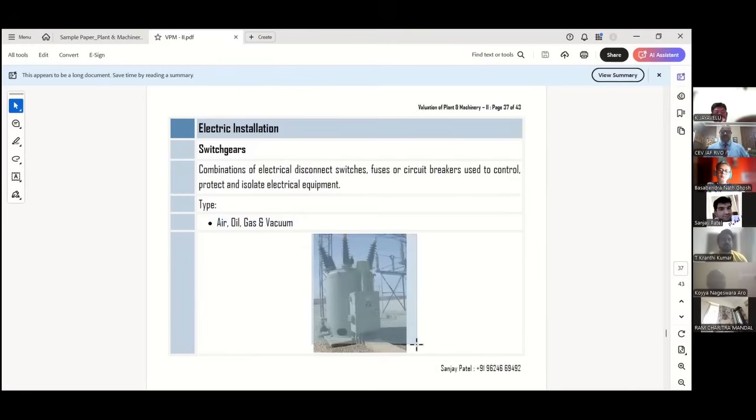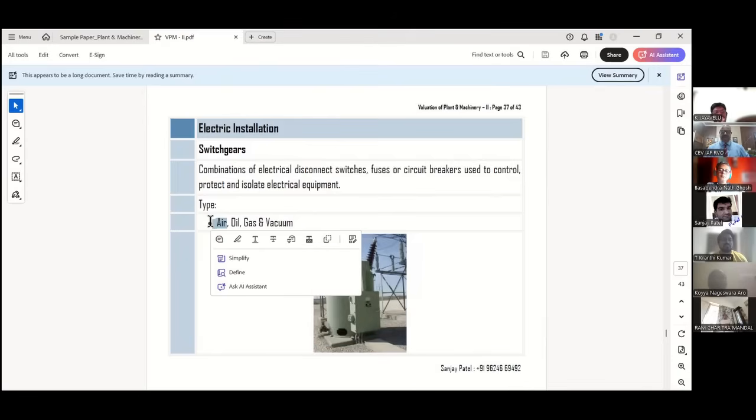If low capacity switch gear, then normally it is an air type. Now we know that whenever there is a connection or disconnection between any electrical points, a spark is generated. Okay, हम घर में भी switch on off करते हैं, at that time also a spark is generated. So how this spark is quenched, based on that it is classified. At low capacity switch gears, pressurized air is filled into the switch gears. Whenever the spark is generated, this pressurized air is released and squeezes the spark.